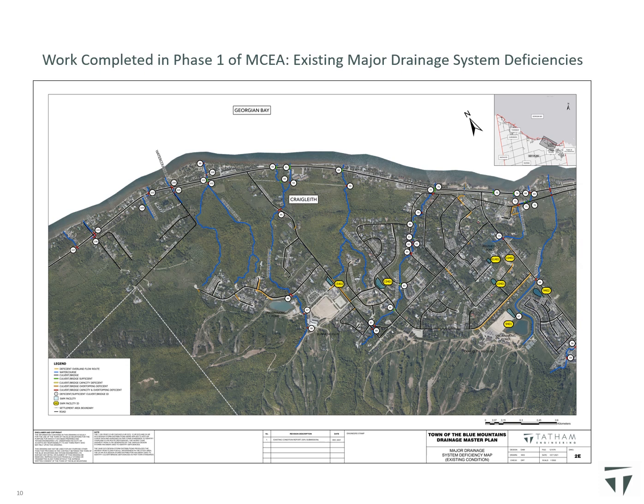It is noted several roads in the study area are owned and operated by the Ministry of Transportation. Culvert and bridge deficiencies on these roads have been identified using the design flood criteria of the MTO. Each crossing has also been assessed based on the depth and velocity of flow over the roadway produced by the regulatory storm, which is the greater of the 1 in 100 year return frequency design storm or the regional storm.